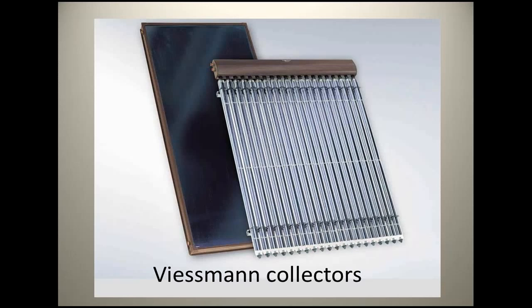Okay, these are the collectors. And here's a flat plate, so they sell both, the flat plate, and then here's the evacuated tubes. Now, the thing about evacuated tubes is that you're only collecting energy in the tube. You're not collecting any energy in the space between, or in the wall of the tube. So it's only the absorber in the middle that's collecting energy. So from a surface area point of view, you see this entire plate is collecting energy in this one, and only the smaller sections in here are collecting energy in that. But these things lose heat, and these things don't lose heat very much. So that's kind of the broad brush comparison.